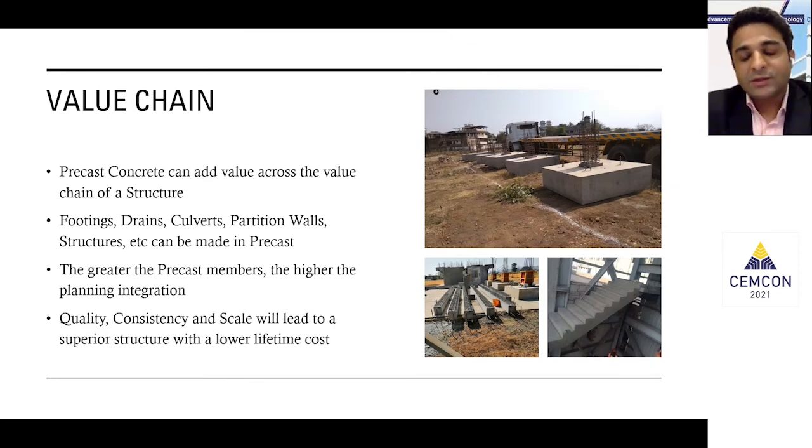The other advantage of precast is it's not limited only to structures. We can use it as footings, we can use staircases, which are part of structures, we can use drains, we can use boundary walls, everything can be done in precast. Now, the benefit of that is the more of our development that is precasted, the more the level of integration, the more the level of standardization. That in itself will give you all the benefits we just discussed. So what happens is that it's one type of technology that's running the show so that you can feed off each other's efficiencies.